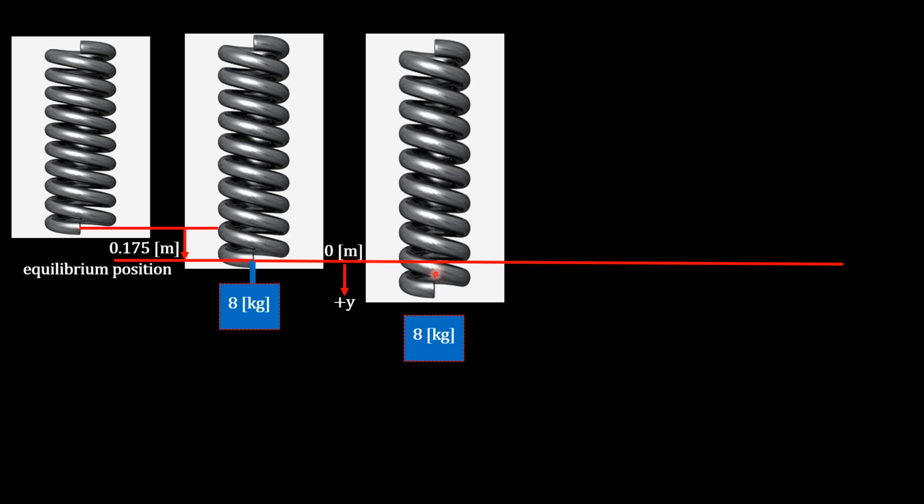In this third one, we displaced the block of mass, with it the spring, an amount of 0.1 meter at 0 second. And as we are displacing, the block reached a velocity of 1.5 meter per second at 0 seconds. Once we reach these two conditions, we release the block.